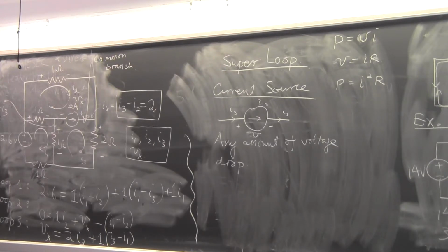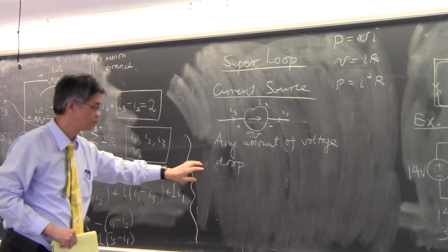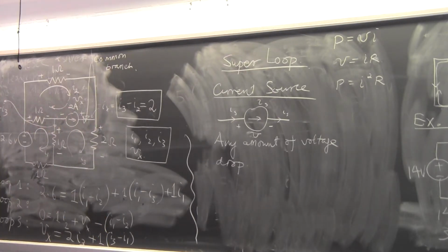But you have to take power from somewhere else. In the case of a cell phone, it's from your battery. It receives a very weak signal from somewhere far away from Chicago, say, some faraway places, but then it makes the signal grow bigger. We'll talk more about this later on. But this is a current source. Its voltage across it is quite flexible, but its current that passes through it is not flexible at all.